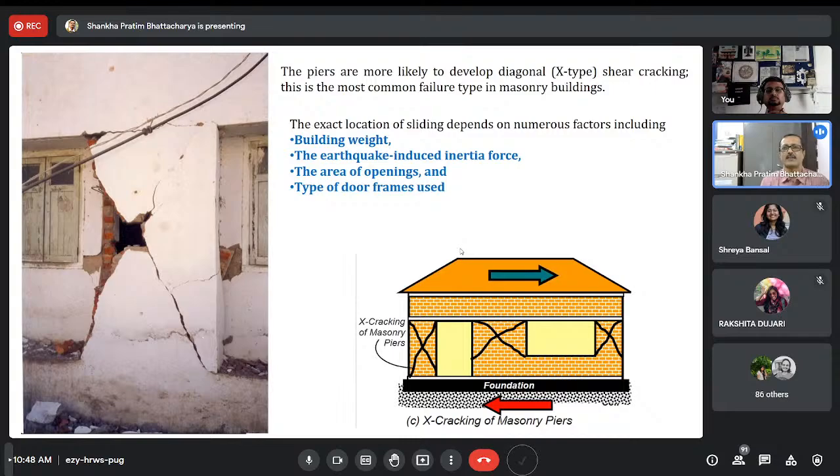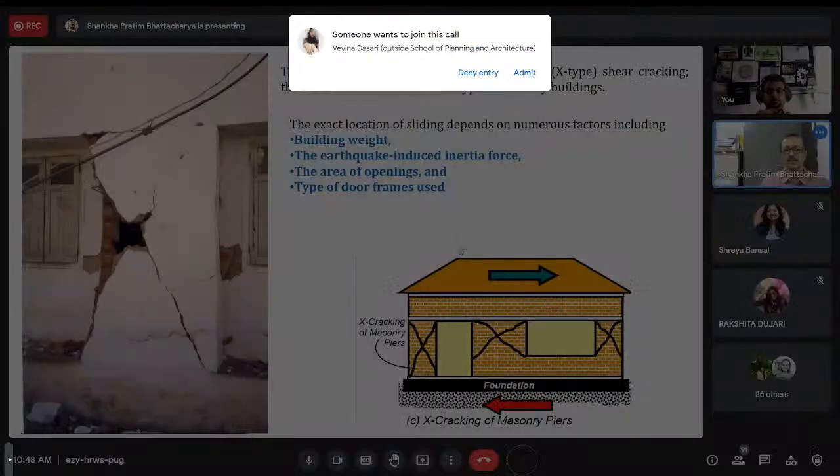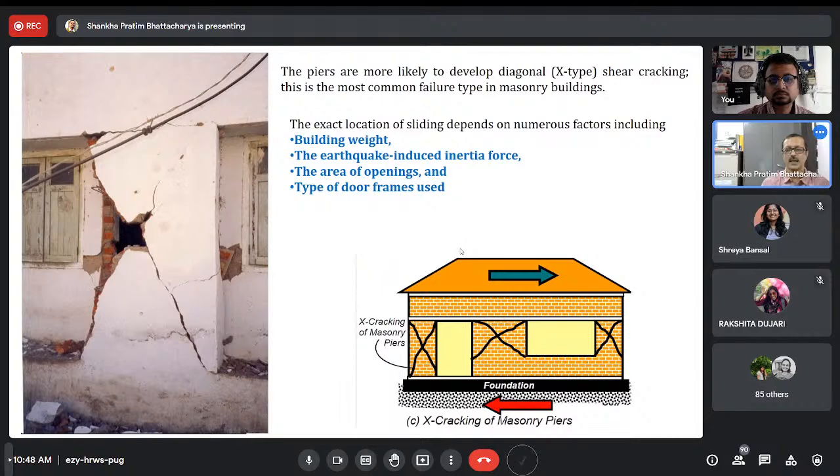And then maybe the earthquake may stay for 90 seconds, or 120 to 150 seconds. Initially, in the first 30 seconds, it will start small cracks, micro cracks. Then it will be followed by the widening of the crack within the next 25-30 seconds. And after that, in the last 30 seconds or so, it will start damaging. So if you somehow restrict the propagation of the crack, you will delay it. This 30 seconds will take 45-50 seconds.